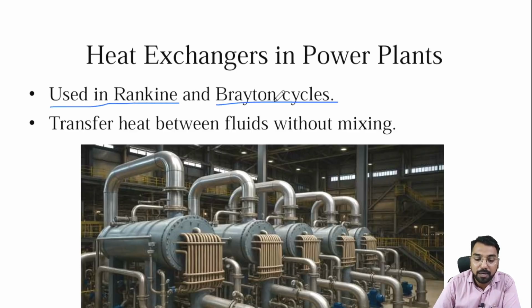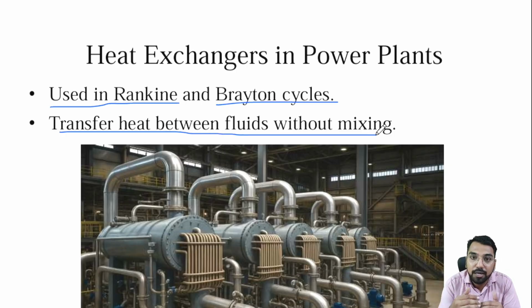So these are the power plant cycles that you are going to see in a steam turbine engineering subject. So, to transfer the heat between the fluids without mixing. What is meant by this? Just like I have said, to transfer the heat from water, which is at a cold temperature, to the exhaust gases, without any mixing, they are not in physical contact; in a convection mode, they are transferring the heat. So that's why the heat exchangers are needed.